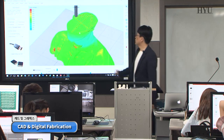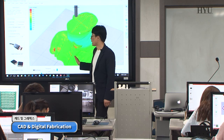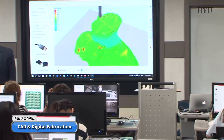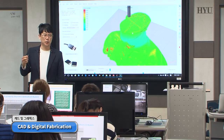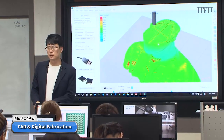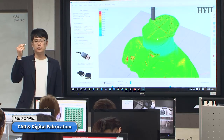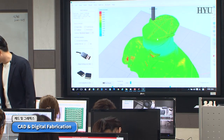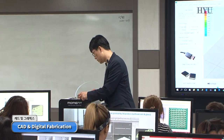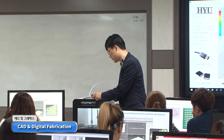So the file for defining this process is the so-called G-code file, and you need to save this into this SD card. So make your object using SketchUp, 3D Max, or anything else, and save this kind of G-code file into the SD card, and then simply plug it in and click print, navigate to your file, and let me print.